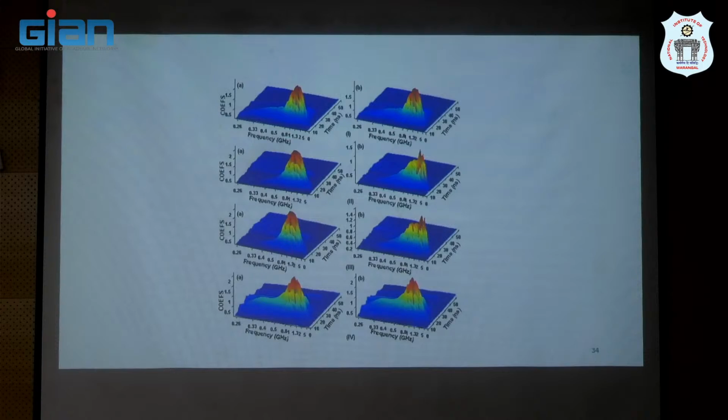Corona will have a different signature, surface discharge will have a different one, and likewise internal discharge in the insulation will have a different one. In that way you will be able to easily extract what is occurring.